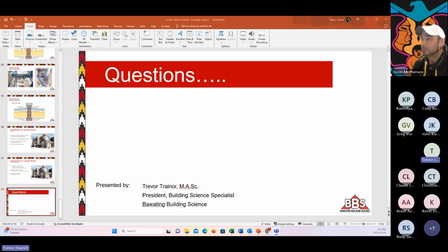Yeah, it's the UV exposure that can break it down. And if in an attic there is some sunlight that gets in there, and if some is exposed because the insulation's moved away, that could be something to worry about. And like I said, in the 80s versions of poly, it was a bigger problem, but modern stuff should last as long as the house. All right, thank you. No problem.